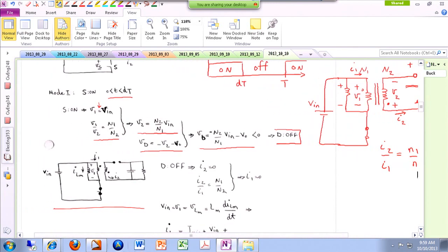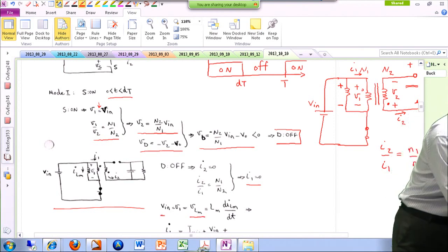All right. So I1 is 0. So that means this ideal transformer that I have, that is kind of representing my real transformer, in that ideal part, nothing is really going on. The only thing that is happening is we are applying this Vn across this magnetizing inductance. Okay? So VLM, which is the voltage across the magnetizing inductance, is the same as the input voltage.